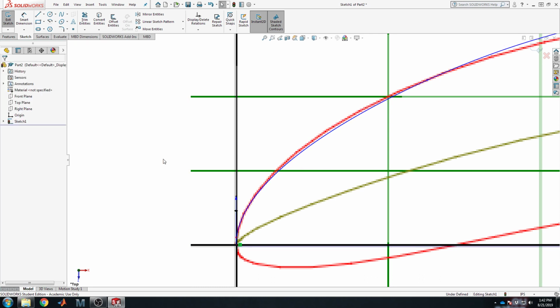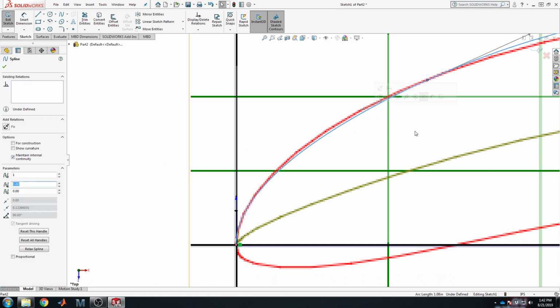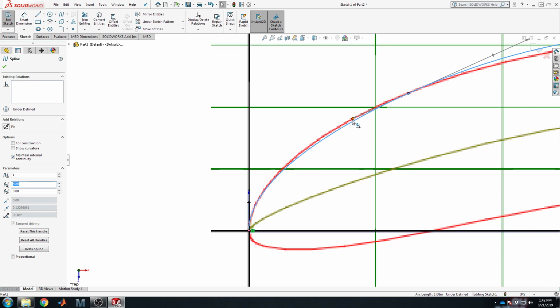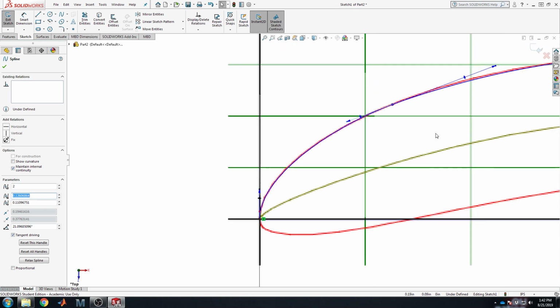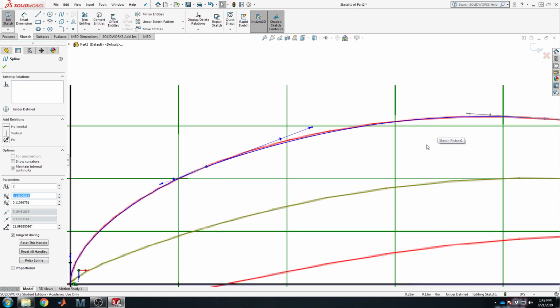And now, yeah, the perfectionists among you might say, well, this is inaccurate, I hate this method. And okay, fair criticism. It's not perfection, but this is probably down in the hundredths or thousandths of an inch, where your eventual sanding of the airfoil on the mold you're making or in the product you're building will have a much bigger influence on the actual constructed shape than whatever minuscule deviation you see here.